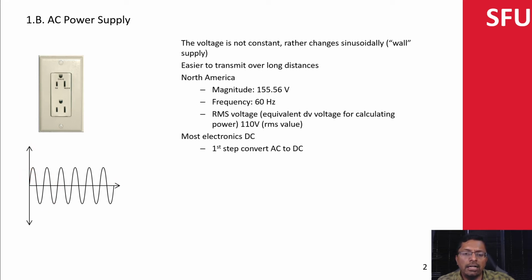If you did that, you'll notice that the average, because this is higher, you basically might get a value over something like this. This is known as the RMS value, or root mean squared, or the effective voltage of the component over here. The multimeter can actually measure these RMS values.